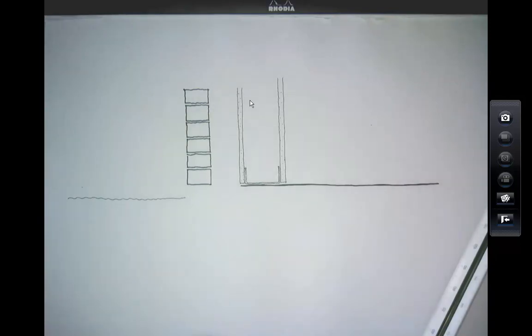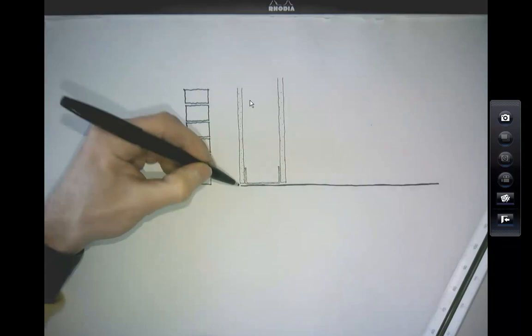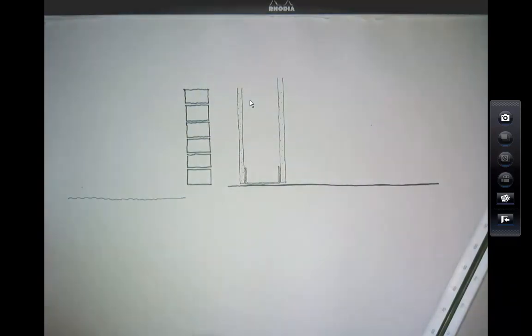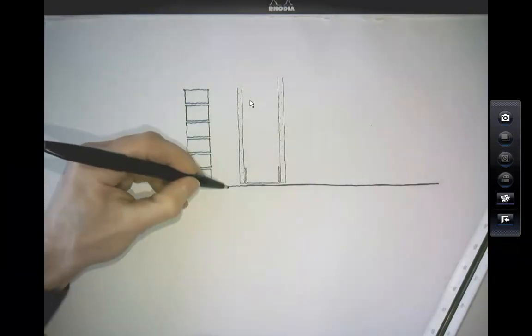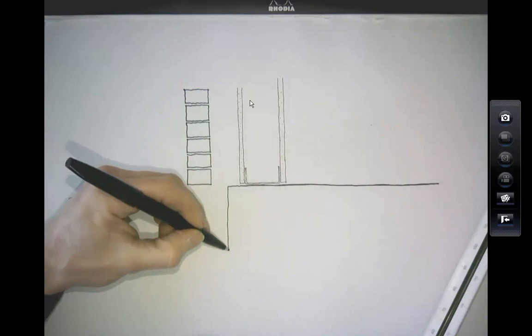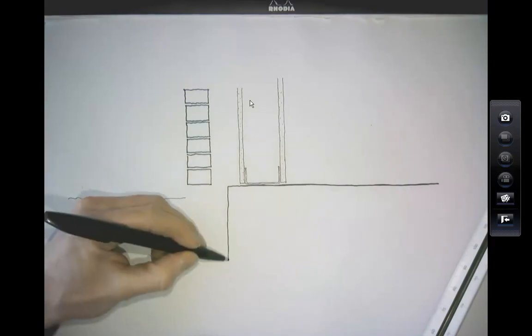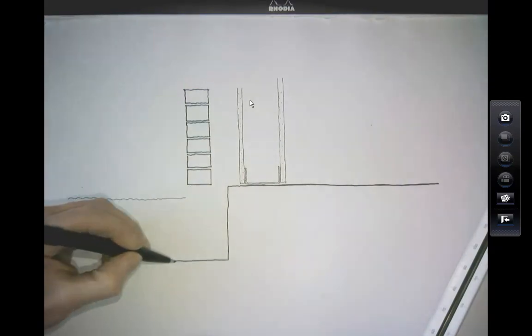So what you typically need to do is to put a toe into your foundation edge. So I'll just draw. You notice I am cheating again. I'm not going to show you that, but I'm not just doing this from memory. So we put this toe into our foundation like this.